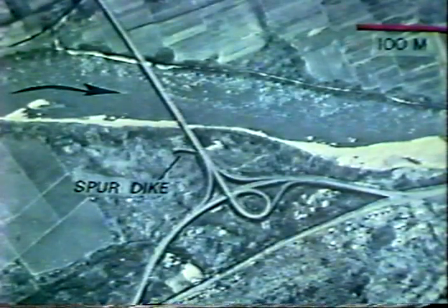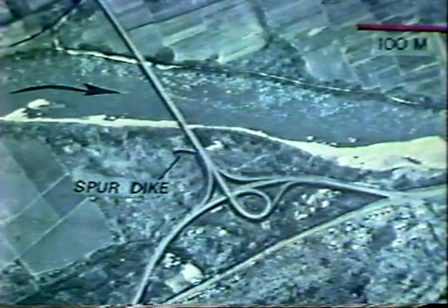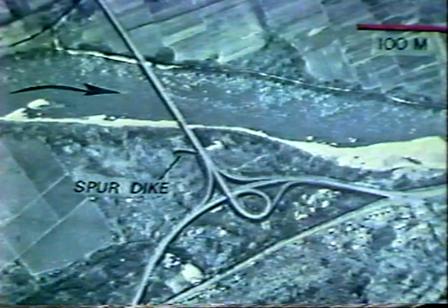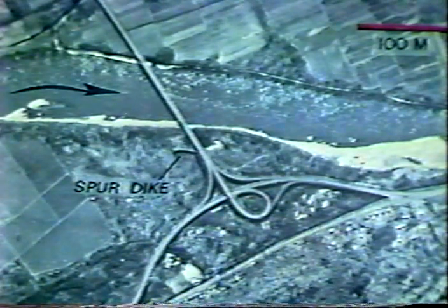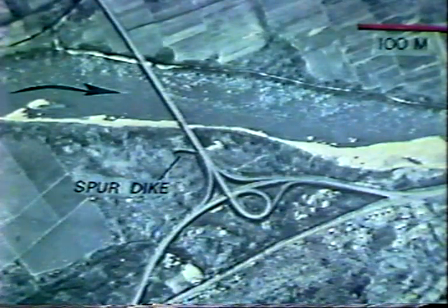A disadvantage of timber pile structures is their vulnerability to damage by fire and vandalism. Overbank flow that is diverted along an approach embankment may produce eddies and scour where it enters the bridge waterway. A spur dike intercepts this flow and moves the point of scour to the tip of the dike.